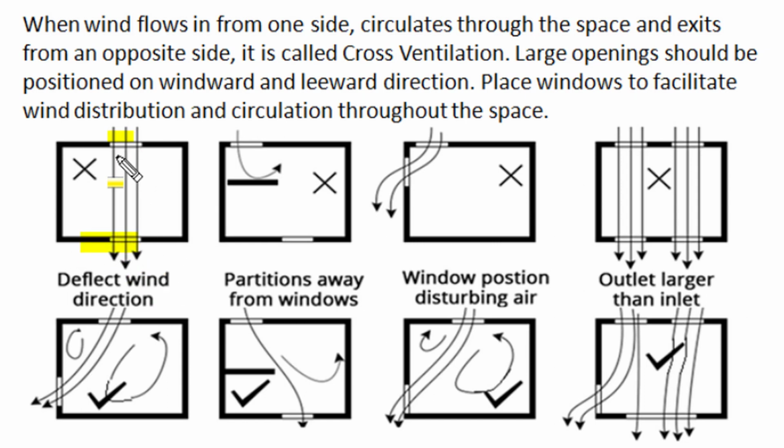And apart from cross ventilation, the air also distribute and circulate in internal spaces. So just opposite facing to each other window opening is not desirable. Any obstruction very close to windward direction is undesirable, and if that obstruction is away from windward direction of window, then it will ensure good circulation and distribution of air in internal space.